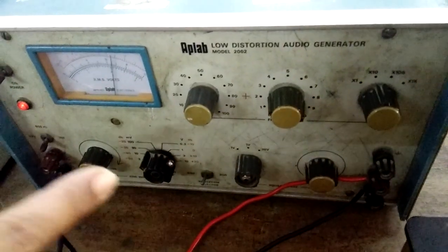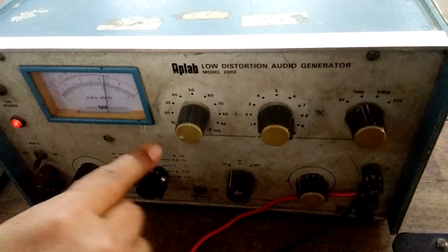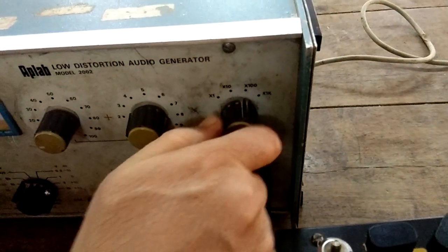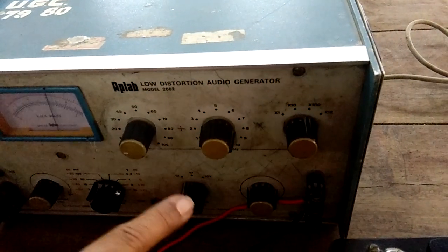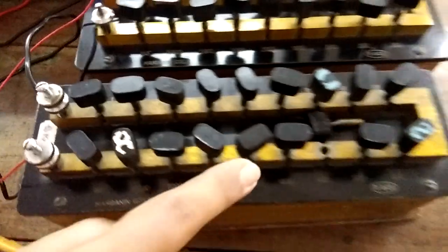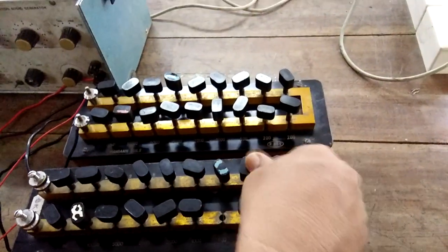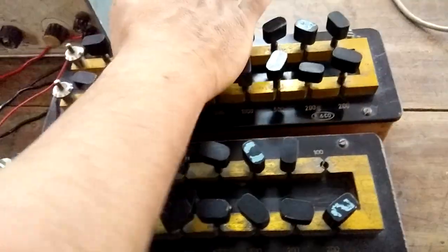But in this experiment, for gain with load, you have to keep the frequency of this generator at 1 kilohertz. So this is on 10 multiplied by 100, so 10 into 100 is 1000 Hertz. The frequency is fixed, and change the value of load resistance starting with, say, 100 ohms. So here I take out the value of 100 ohms, press all keys tightly and record the output voltage.